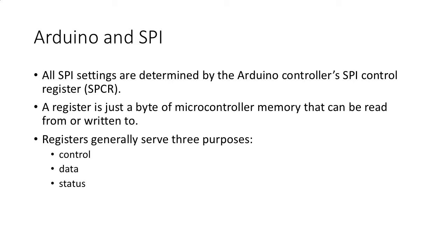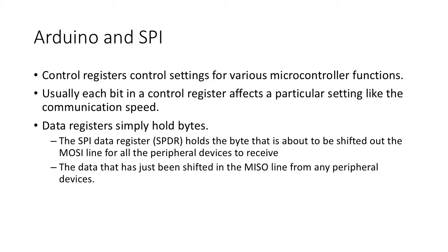There's an SPI control register, which allows you to not just fill memory in advance of having it transferred, but also allows you to change the status and control of the transfer. There is no error correction. There is no automatic retransmission request, and there is no flow control.